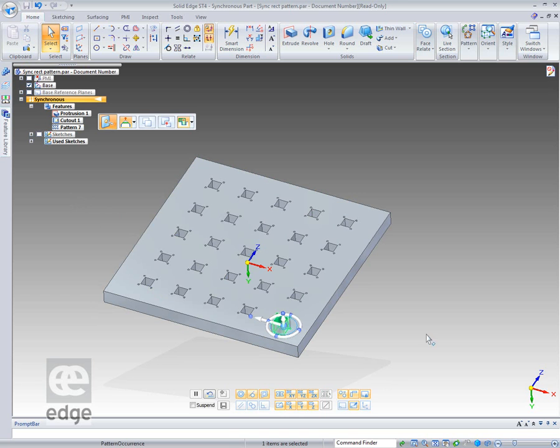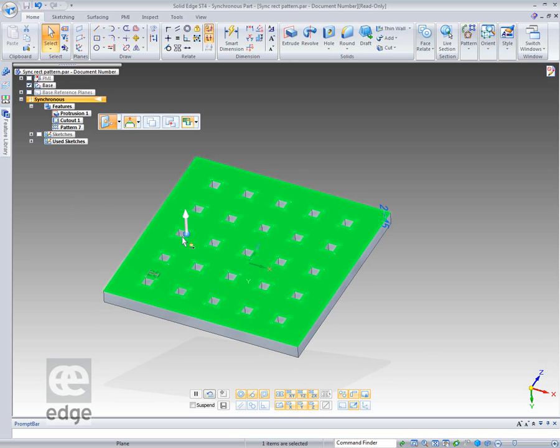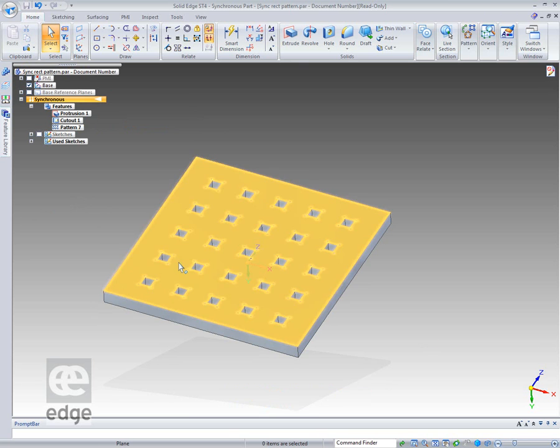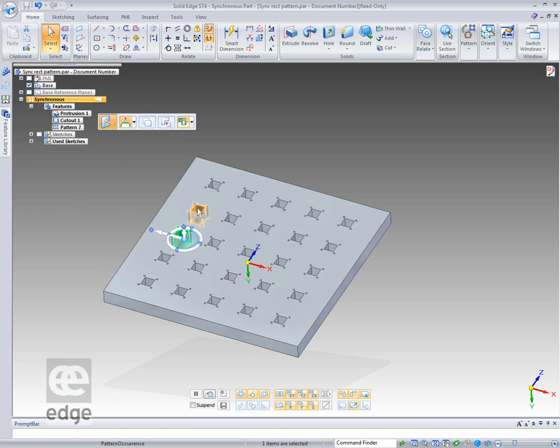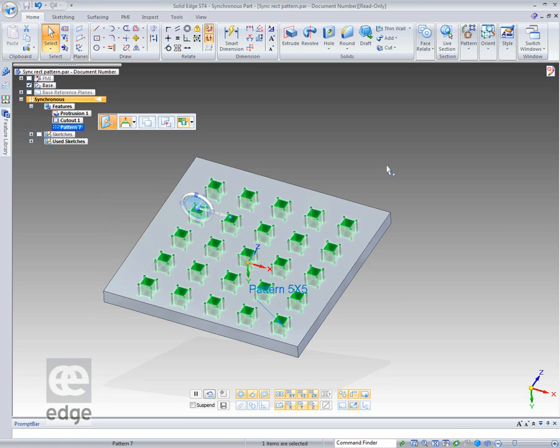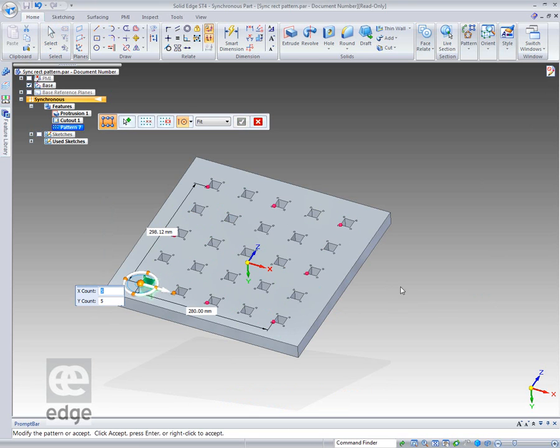If I select an outside one, or I let my cursor rest for a moment so I get the ellipsis, the 3 dots, I can right click and select the pattern. If I want to edit the pattern, you'll notice it says pattern 5x5 down in there. I just click on that and I'm back to my original count.